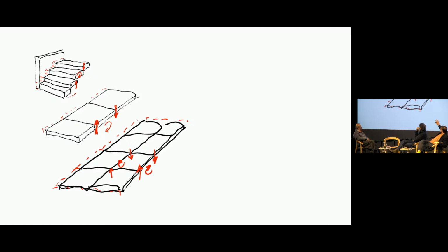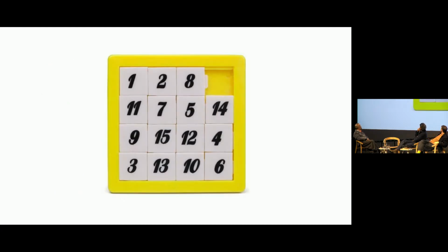The idea that you could make the staircase flat instead of steps, so you can make a bit of floor with tiles working in exactly the same static way, and then you can build another one on the side of the first one, and then you can start to create a reciprocating torsional flat structure in unreinforced stone. And it occurred to me after figuring that out that it's exactly like this.